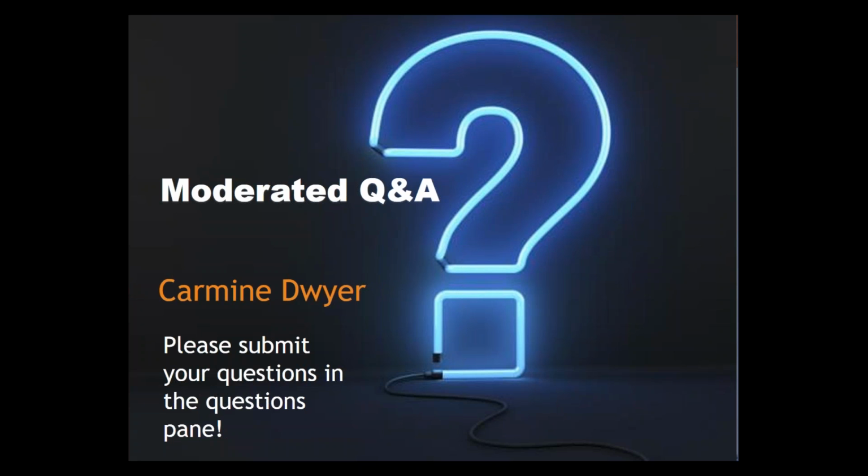Okay, thank you, Anna. Next question says, have you experienced any problems with epoxy on new asphalt pavement as the marking cures and shrinks? And what is the curing time on asphalt pavement before it can be marked with epoxy? Curing time of the asphalt, we wait 14 days before we place the epoxy. And I have not had any issues with epoxy on new asphalt.